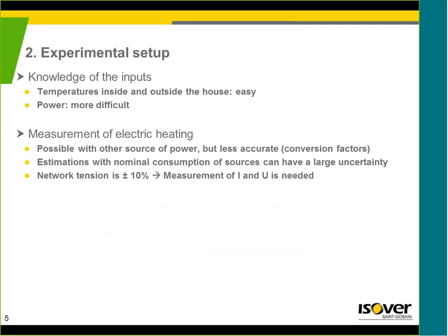You really want to measure the power. We actually realized that measuring with several systems like an ammeter, I don't know the term in English, well, the measurement of only the current will not be enough because the network voltage can be variable. So you want a real measurement of the power, and then you will have good information. But you also want, at the same time, to reduce the unknown power sources.